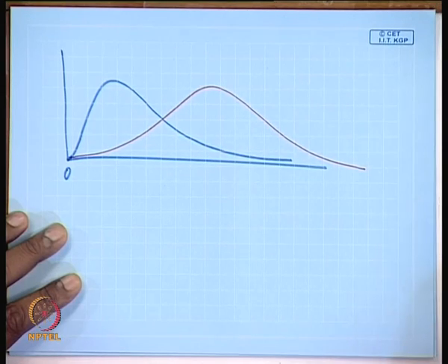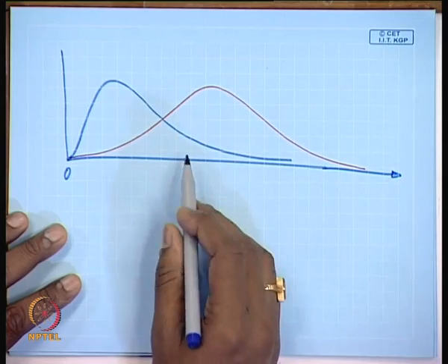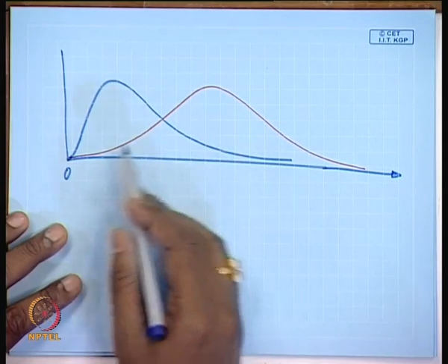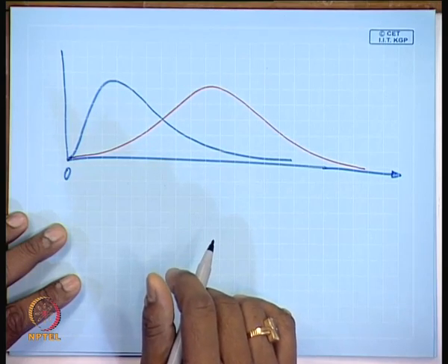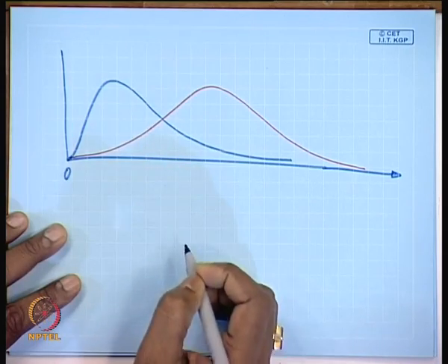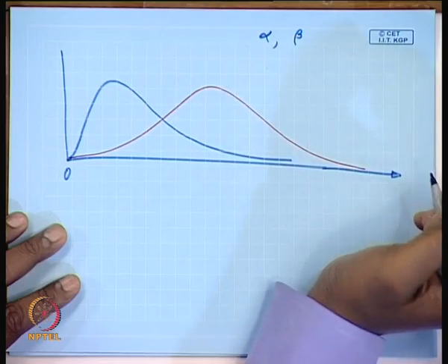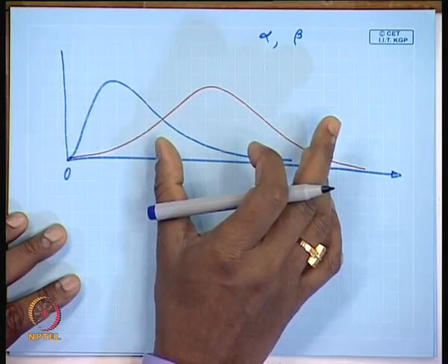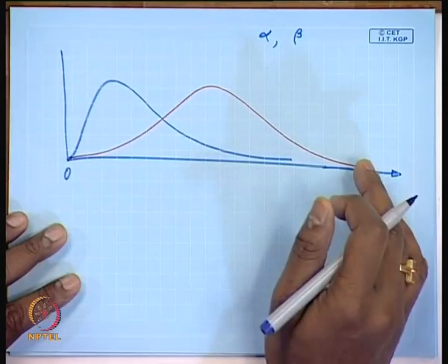Sometimes for very large rivers, the flow has a basically symmetrical shape, like a normal distribution, but again the lower bound is 0. So just by adjusting these two parameters, alpha and beta, of the gamma distribution, you can control the shape, from the exponential to the positively skewed, even to the symmetric.